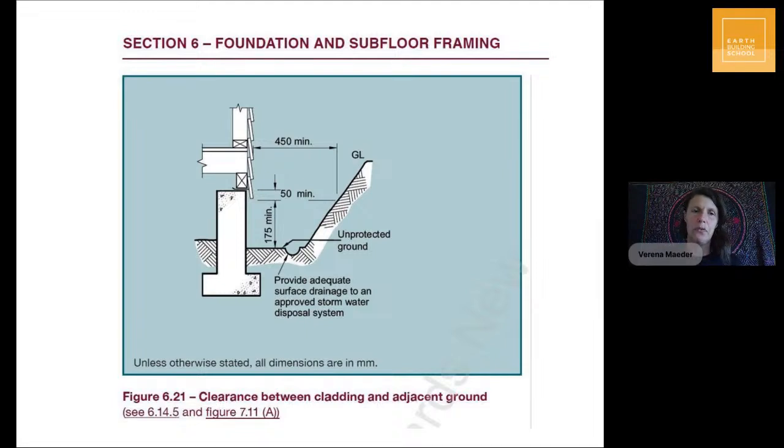Some of them are also concrete walls that are under a timber building. So you have a whole wall that is your foundation. Sometimes you have concrete piles or even timber piles, so treated timber piles. And when you're designing a small timber building, it can be like a 10 square meter building. Some people actually like the idea of being able to lift the building or drag the building out of the location it was built later on.